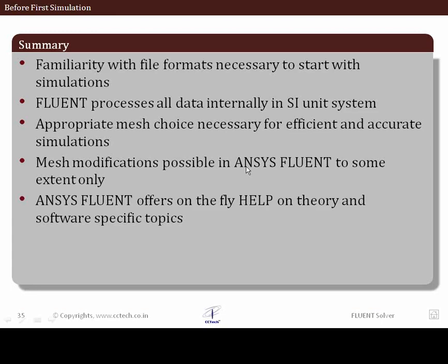So as we can see here, ANSYS Fluent is quite strong, and we should be familiar with some specific things like the file formats and how we should deal with the unit system in ANSYS Fluent, which internally is an SI unit system. So if we are interacting with the source code through a user-defined function or through a profile file, we should be aware that all the inputs need to be given in the SI unit system.